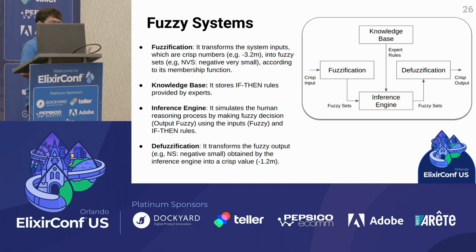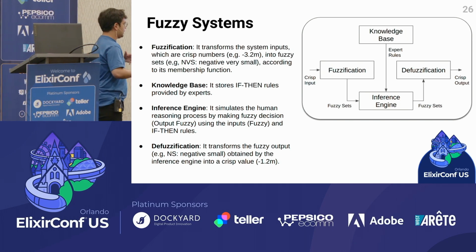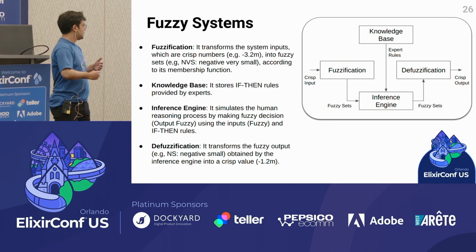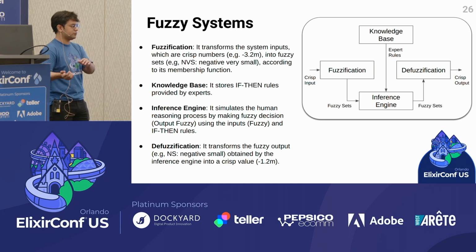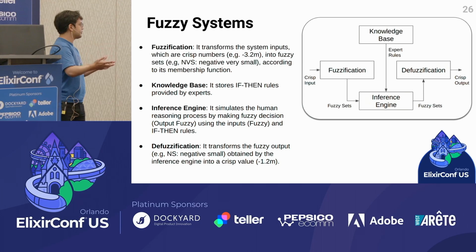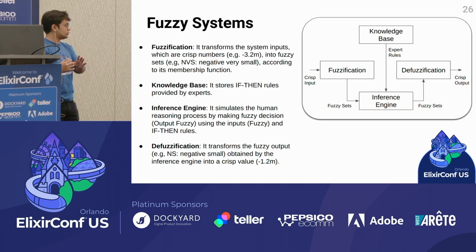So the idea here is that in real life we have raw data, floats, and crisp inputs. So the first step is to pass those values into the fuzzy realm by making a fuzzification phase, and then we can compute all the rules that we defined previously, and we will have output, but in the fuzzy realm, which has membership values for the given sets that are related to the output.